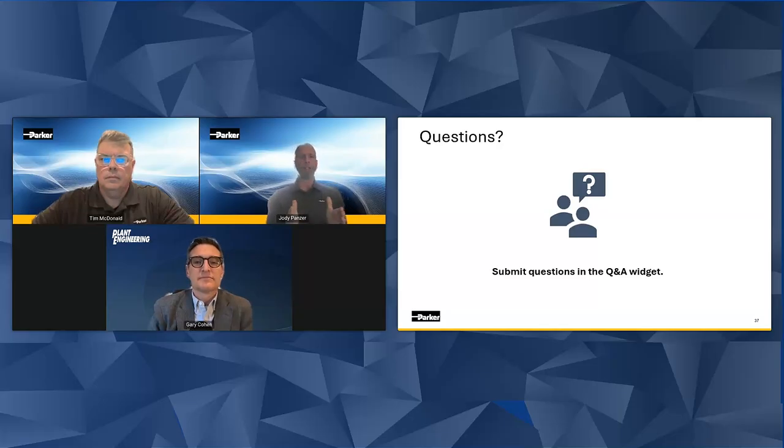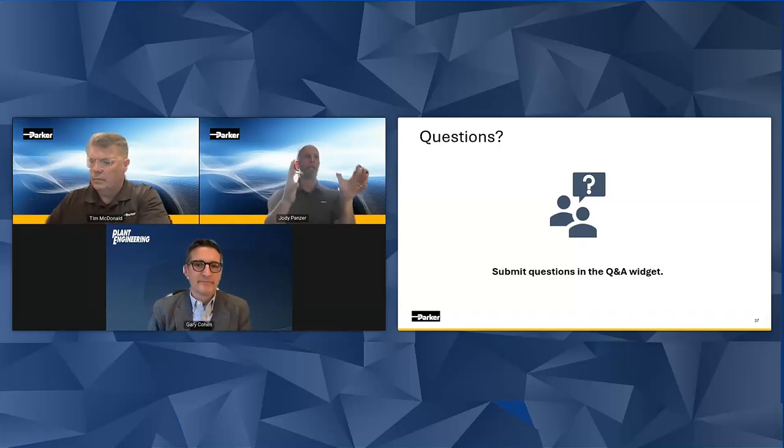We want to follow those parameters. Where we run into trouble is if we have too many 90s in an area and we create what you would call a hammer. You know, it can be done in water applications where there's water hammer, or there can be air hammer where there's too many 90s, and what's happening is the air is hitting the pipe, dead ending, and it's constant. That will end up shaking the pipe, and then you can show issues.